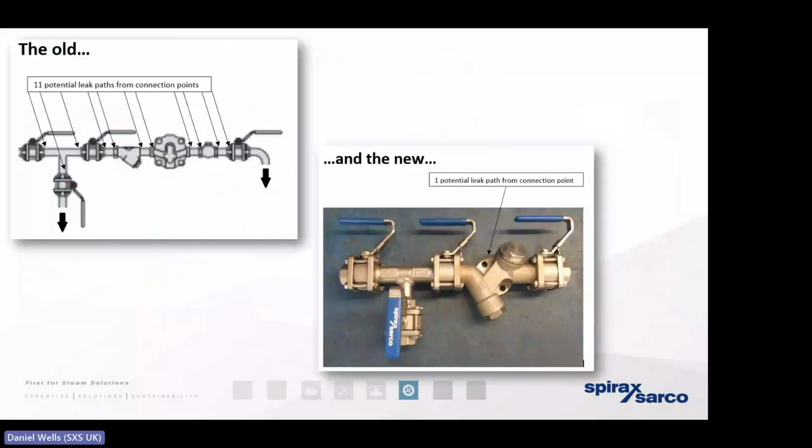Well, so far we've spoken exclusively about the steam trap itself as an individual component, but it's important to remember that a steam trap should be considered as a station. We need to install a number of ancillaries to ensure that we can service and maintain that steam trap appropriately. So we may choose to have any number of isolation points upstream of the trap, a Y-type strainer, a check valve to prevent backflow of condensate when it's taken offline.